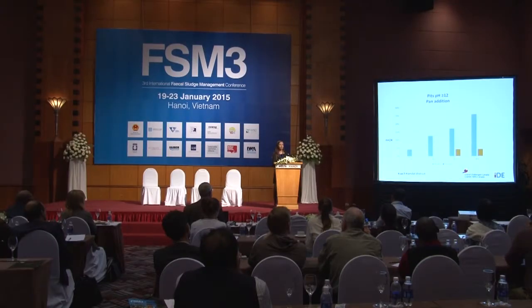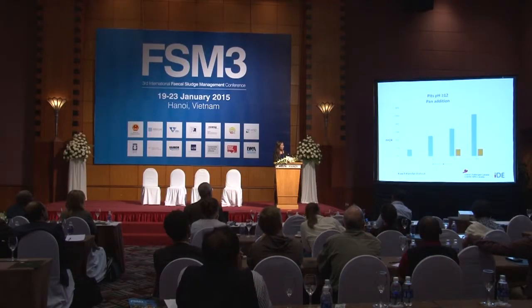Here we're expecting to see an increase in pH. As households keep doing this, the pH in the pit increases. So the weekly additions seem to be working a lot better than the per-use addition. This might also have something to do with our weekly visits, which probably act as a reminder for the household to add the lime. For the per-use addition, users probably forget to do it on a regular basis. So with the weekly usage, we had up to 25% of the pits reaching a pH of 12.